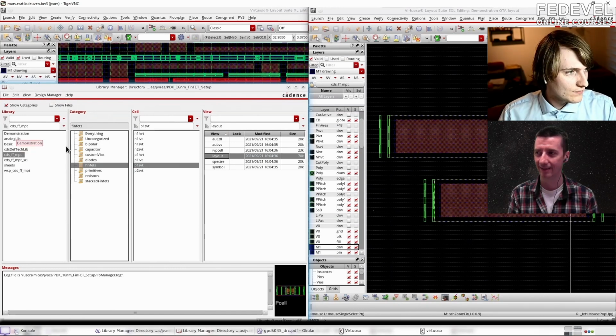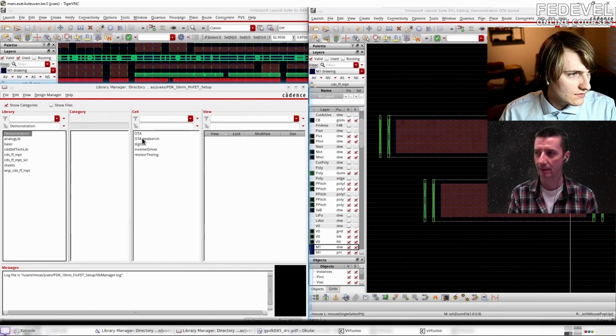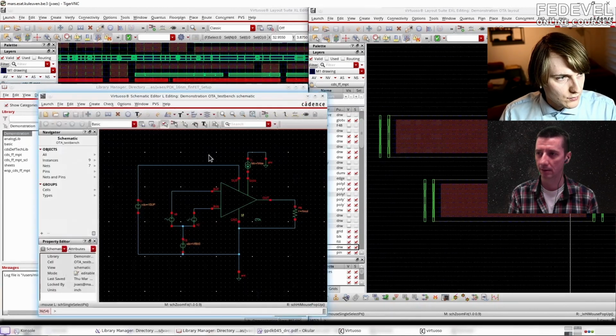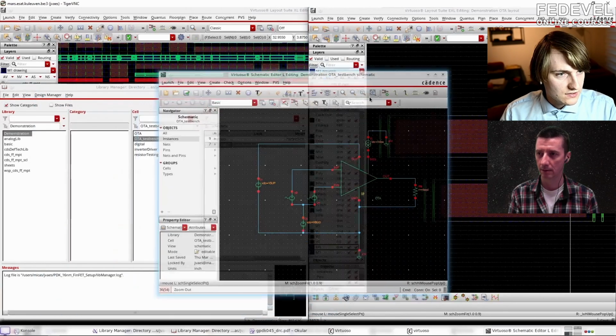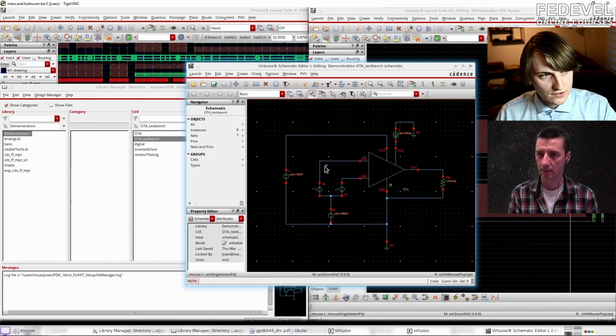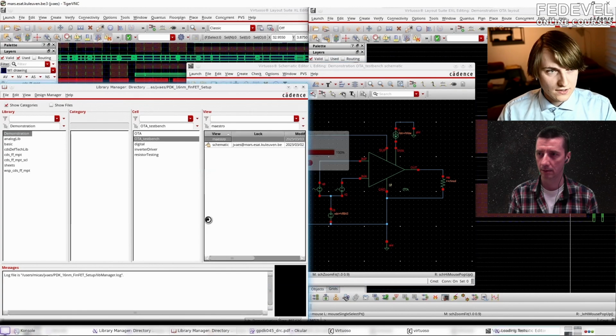And they provide this also as part of the PDK. And so, for example, this OTA I just showed you, this schematic, I can then put it into a test bench, right? So this is that cell I just showed you before. And I connect a load resistor and some input sources here, a supply, and then I set up a test bench for this.